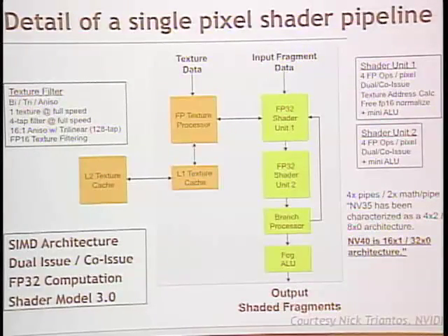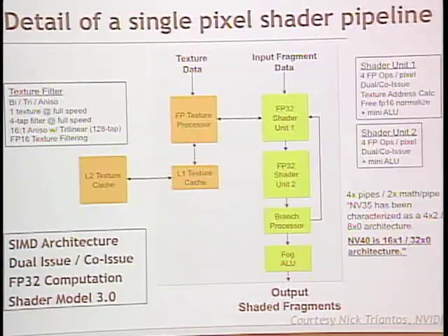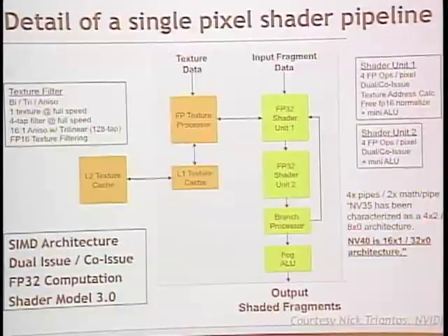Most of it's scalar. So today, NVIDIA has decided we're not going to build 4-wide hardware anymore. We're only going to build 1-wide hardware. And that's what they've done in their latest chips. ATI has not done that yet. ATI actually has 5-wide hardware, so they can do a 4-wide operation and a 1-wide operation at the same time. But they feel that it still makes sense to have 4-wide hardware. That's sort of a difference between the two companies.